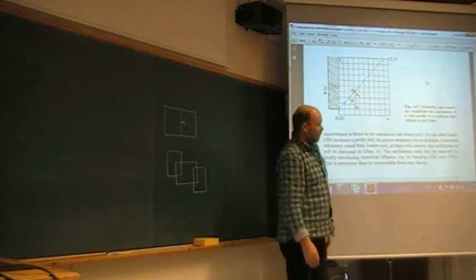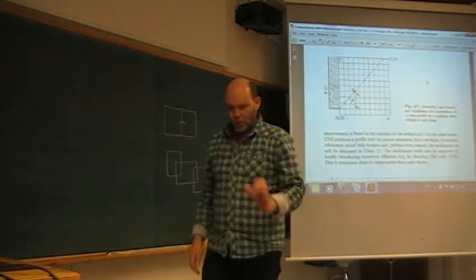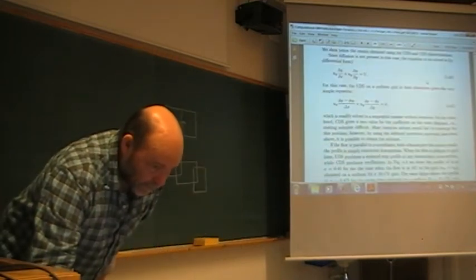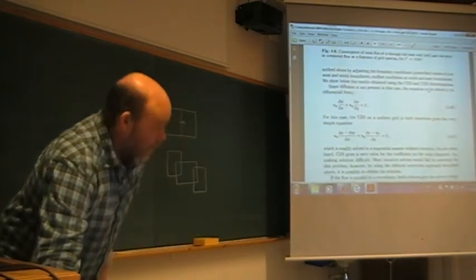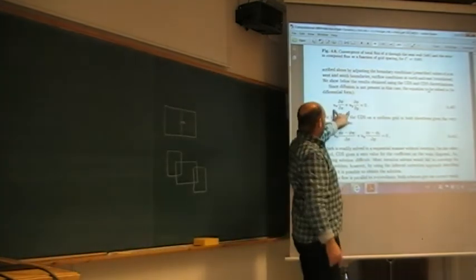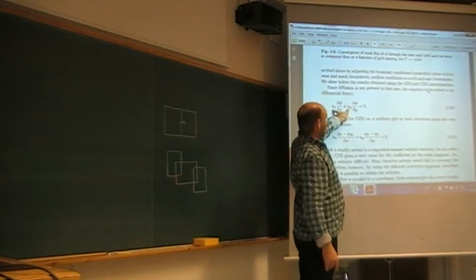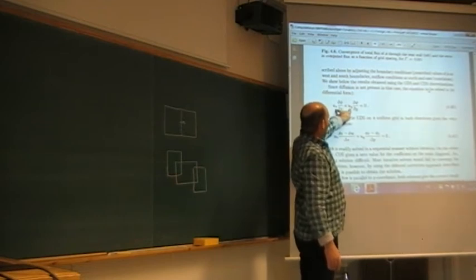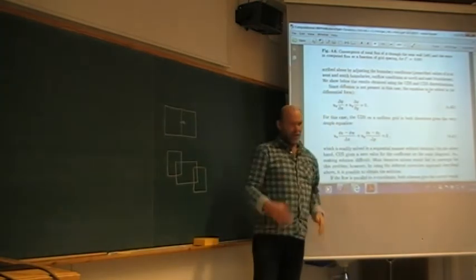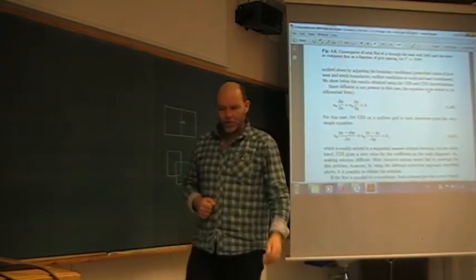And my equation is only the advective part of the transport here. It's only this one. Velocities are given, they are constant, equal to 1, say. So this is then equal to 0. I don't have any viscosity, hence this gradient should be sharp.